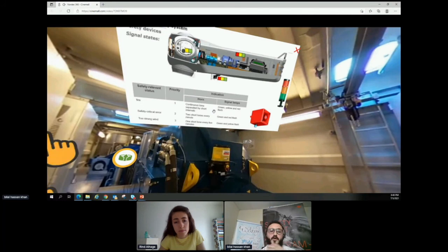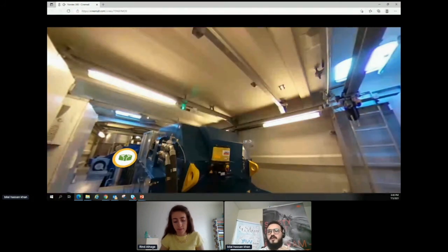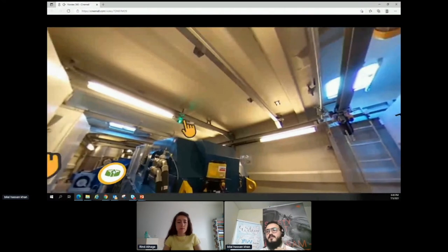And if you have too high wind while we are working in the nacelle, here I would like to add that in the tubular tower, if you want to work in the nacelle, then your wind speed must be less than 20 meters per second in the 10 minutes average wind speed. So if you are working here and you have high wind, then you will see that the green and yellow lights start to flash. This was the information. Let's go outside and visit the hub.